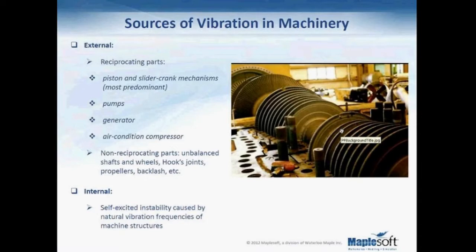The total engine torque is the combination of the individual fluctuating torques that are coming from different cylinders. For example, for a four-cylinder internal combustion engine, the total torque is the sum of the individual fluctuating torques that come from four different cylinders. This can be very complicated, and if we have a higher number of cylinders, for example 12 cylinders, or a double engine driveline system, this can be very challenging to understand and analyze.